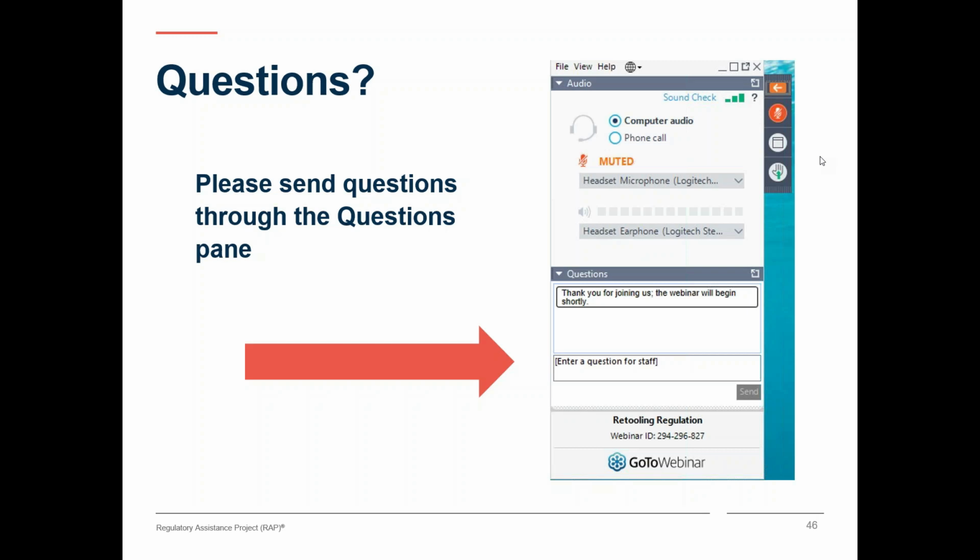One thing I want to caution people, as I looked at the question and referred to an article that I'd seen: the system lambda costs may be evening out, and in fact in Hawaii and other places, they ultimately will be basically zero once you have a 100% wind and solar and storage system. You have no variable costs, so the dispatch costs at any hour will quite possibly be zero or near zero. And certainly in the Western U.S., where we have a dramatic surplus of gas-fired generation, prices very seldom go above the cost of dispatching gas-fired generation. But the question always has to be, look at all of the costs that are required to provide service in a time period, not just the short-run variable costs.